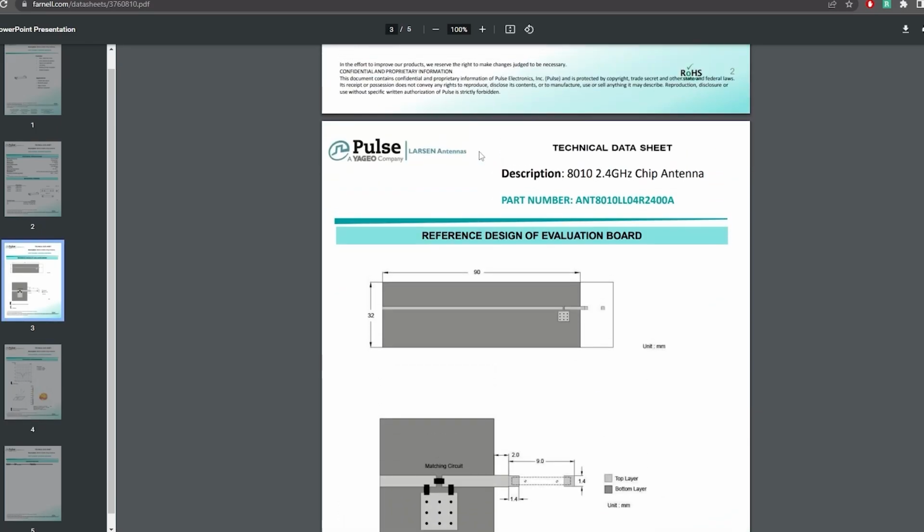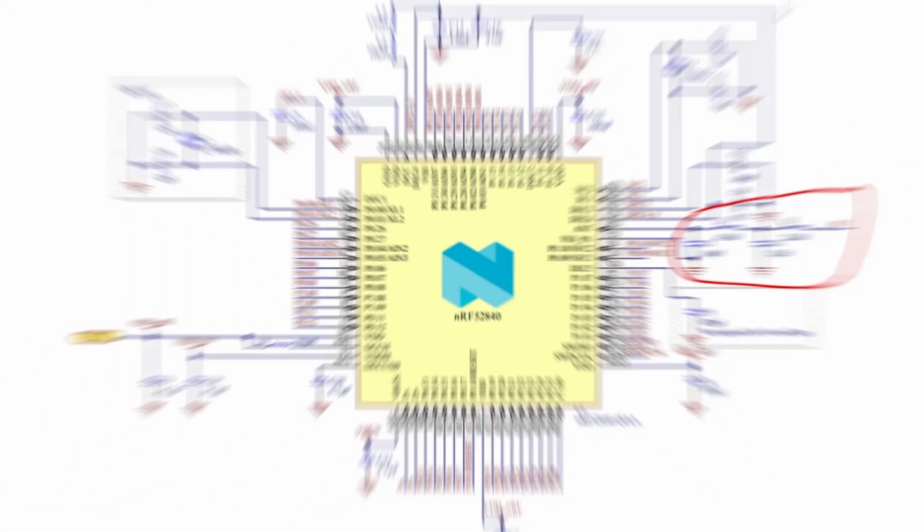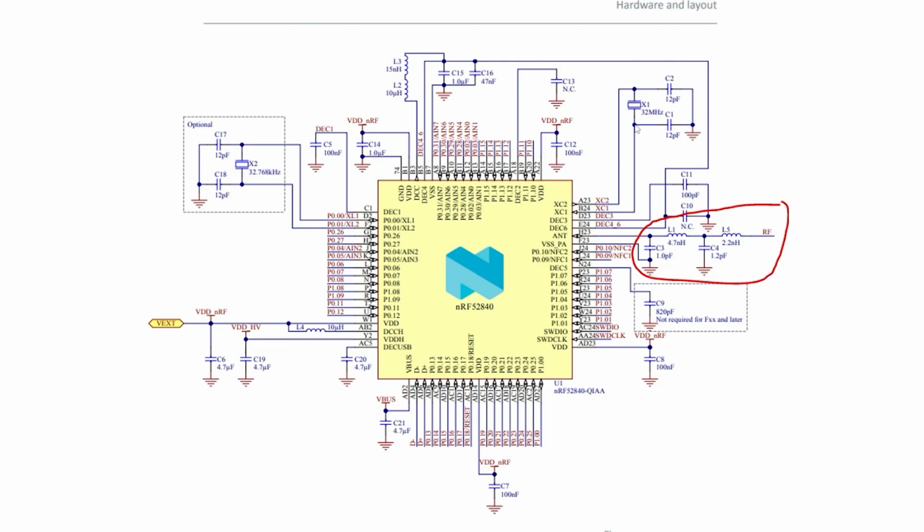Well, I know something else that has a schematic that I can use as a reference, and that's the microcontroller that I was using. So here we are in this microcontroller reference schematic from an nRF52840, and it was this exact piece of circuitry here that I used for that Bluetooth antenna. You can see here it's got a pi filter and an inductor, two separate parts. This was the exact circuitry. In fact, I used this whole entire thing here. I simply copied and pasted because they gave it, and I know it'll work, and lo and behold, it did work in the end, because I just attached the antenna in front, and I copied the antenna layout guide and what the manufacturer specified, and so on and so forth.